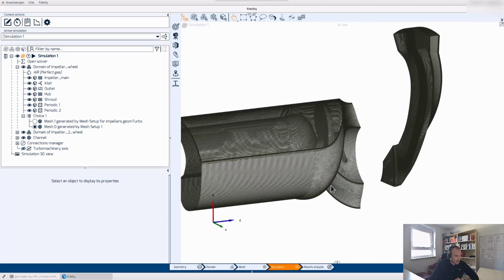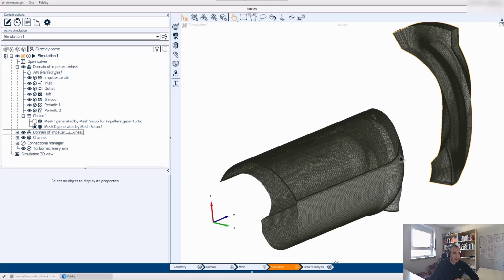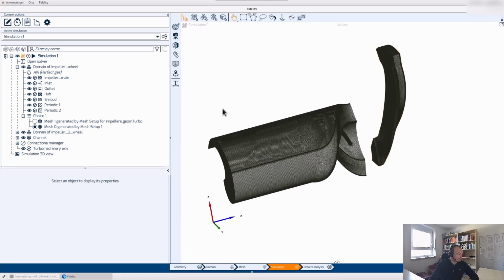And then, as you can see, now we have the unstructured domain for the inducer and the structured domain for the radial pump. And now you can simply continue and set up your simulation, apply your boundary conditions, and run the case. Also note that later you will still be able to have all the turbo capabilities for the post-processing. So you will be able to calculate the meridional average, the blade-to-blade view, everything you're used to when you use a structured grid. You will also be having these options for the unstructured grid that we created. So this is not a limitation.